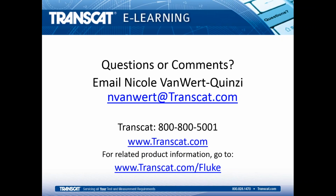Okay. Do you have any suggestion for checking plastic-coated wire thermocouples with only a small metal part of the thermocouple that's exposed? Okay, so when you've got the tip of the thermocouple exposed, you want to make sure that it's not touching the metal on the dry block. So when you have it inserted, you got to lift it just a little bit from the bottom of that insert, because it's conductive material and there's a heater going, and so you're going to get some electromagnetic interference if it touches the bottom. So that would be one issue.